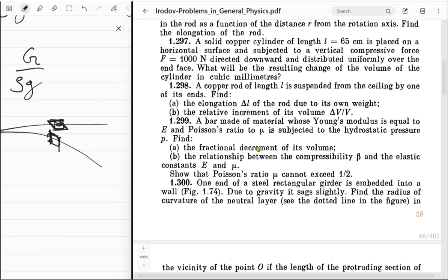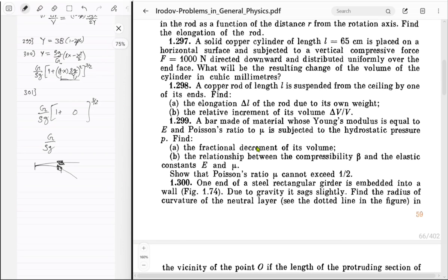So it's not just the slope. It's the, how do I explain this? After the rotation, if you don't shear, you will get the slope. If you shear, you don't get the slope. For this surface, the slope is not the same as what it was before. Does that make sense? So that thing, gamma equal to dy upon dx, that is not correct, right? You should not do that. I repeat, you should not do that. Instead, the correct way of doing this is actually a very complicated way.